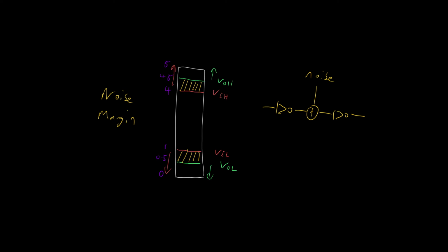In an analog system, as the signal propagates through resistors, capacitors, transistors and whatnot, you get more and more noise. This does not happen in a digital system because logic gates tidy up the signal. The input might be close to, say, 1 volt in this example here, but the output is then guaranteed to be above 4.5 volts.